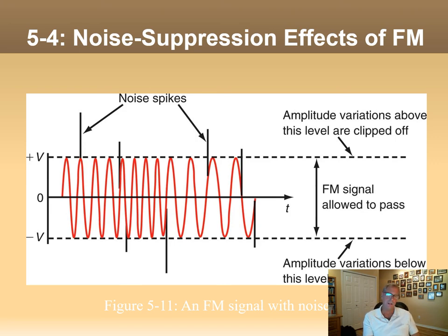If that's not shielded properly, that will leak into your other receiver, and that can be interpreted as coherent noise and mess with the FM receiver. So FM is not completely impervious to noise, but it's much better than AM, obviously. So the stars have to line up just right for you to hear noise in FM.